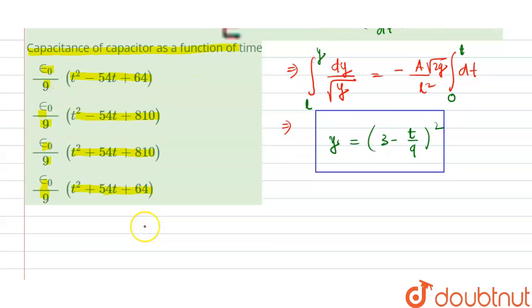So now in order to find the capacitance, for this first one, let me write here C equivalent. These are a parallel combination. So we can take area 1 times epsilon divided by the spacing between them, which is L, and this is area 2, and epsilon into k divided by the distance L.